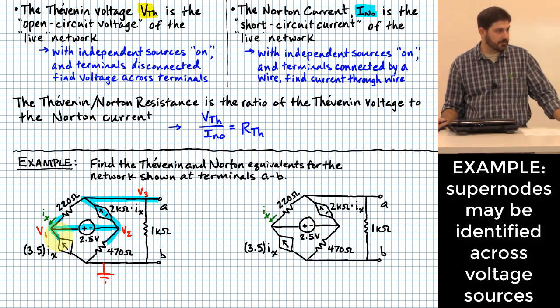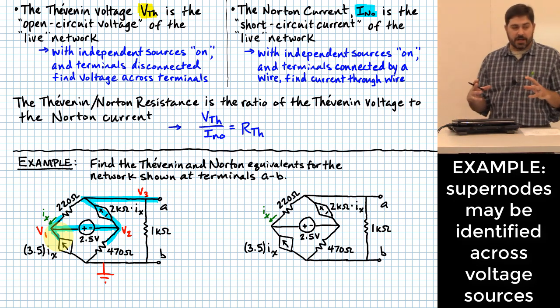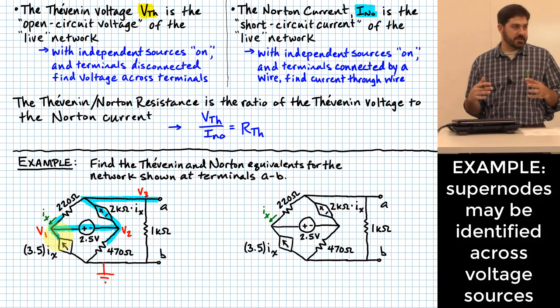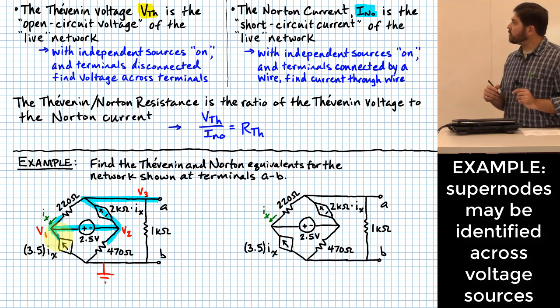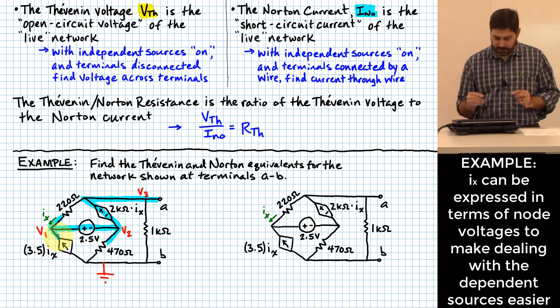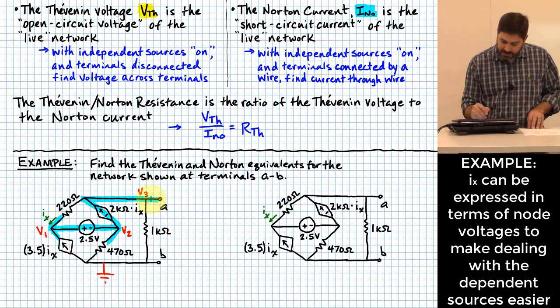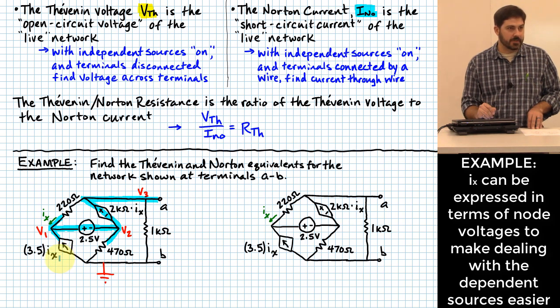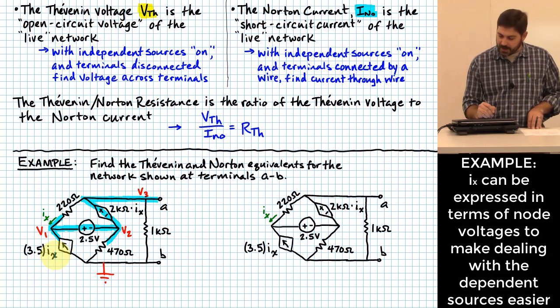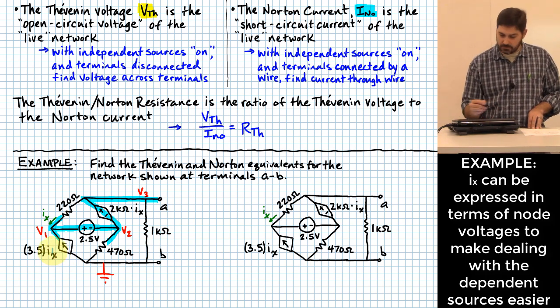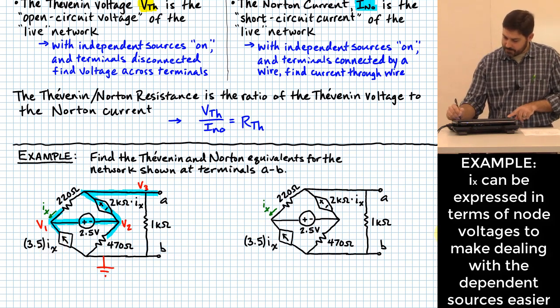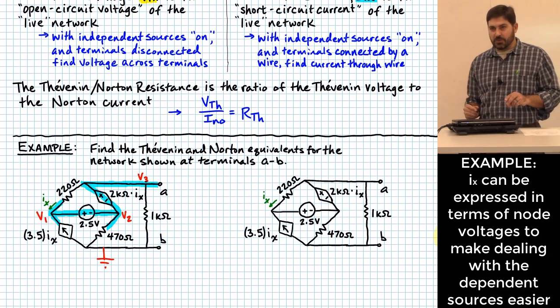Okay, with me so far? So that's a big supernode on which I am going to do KCL analysis. I do want to do that, but before I get to writing that equation, I notice one thing: at least one of my terms is going to include this Ix value. Is there any way for me to maybe simplify this process by first coming up with a relationship for Ix? I see a few of you nodding.